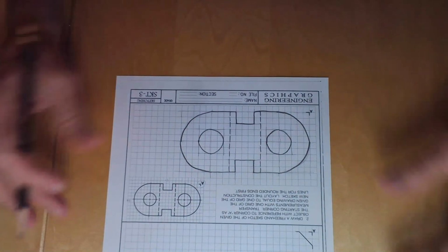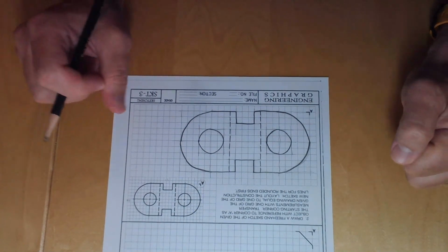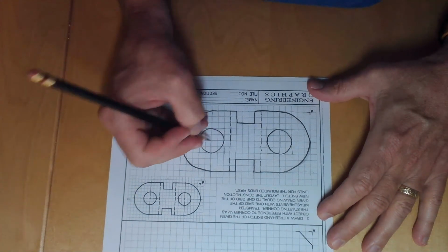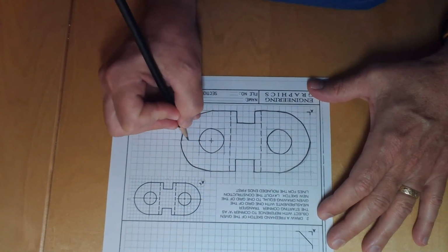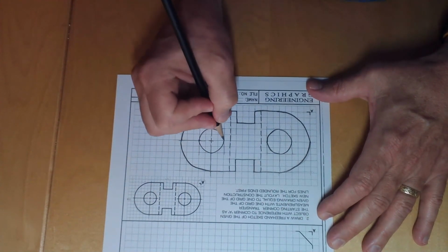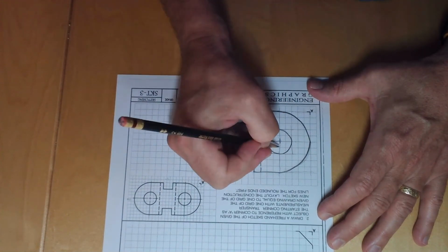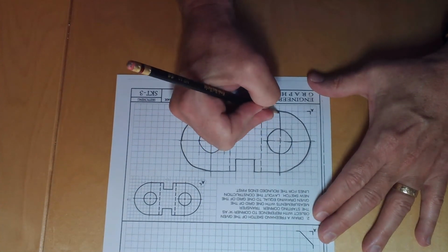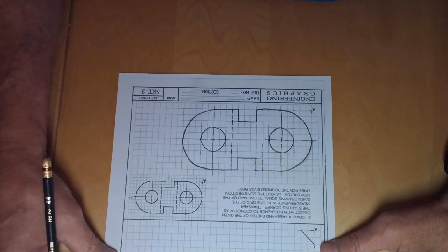All right. What do we do with the construction lines that are left there? Absolutely nothing. Now I would also probably add, or we're going to need to add, the center marks here. Those are thin weight lines like the hidden lines, so we're just going to do this. And we already have construction lines there, so I don't need to do any more construction lines. There we go. Okay, so that's our first sketch done.